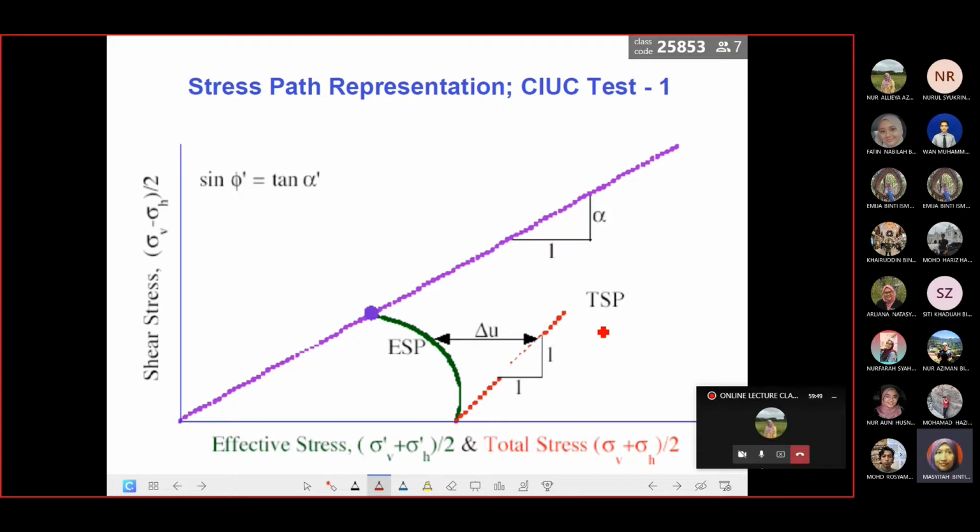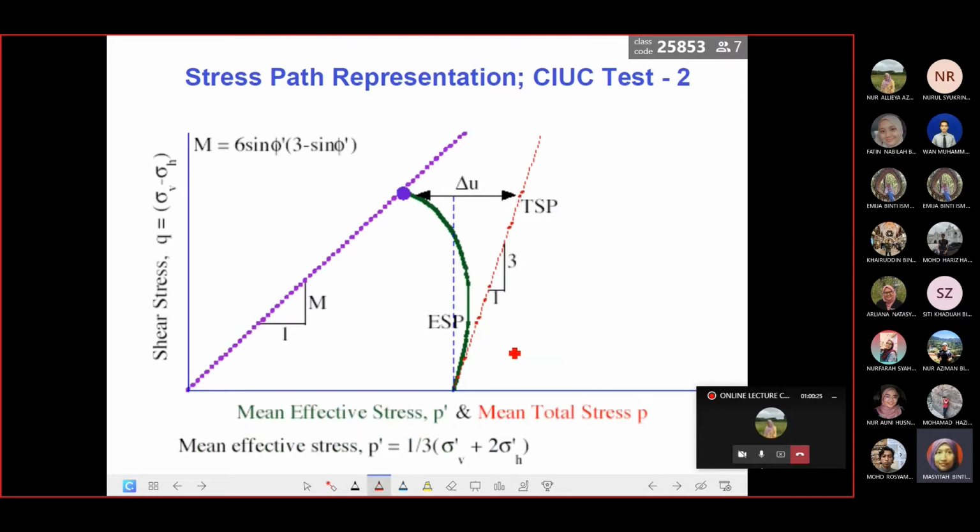As I said earlier, whether in sigma 1 or sigma 3, to get the effective stress you have to subtract the pore water pressure. So when we plot the maximum shear stress at each Mohr circle in the effective parameters, you will get a curved line until the curve touches the failure line. That's the point or condition where the samples fail, either on site or through experimental investigations.